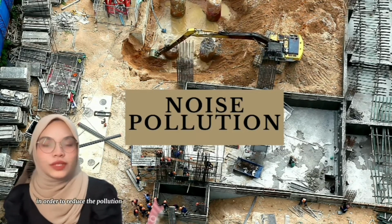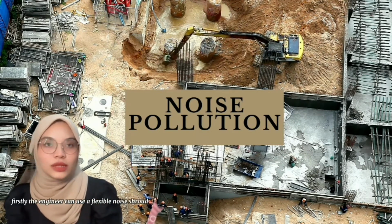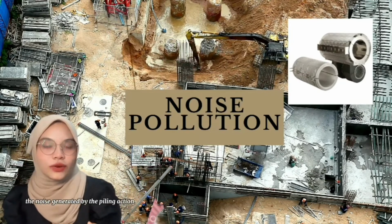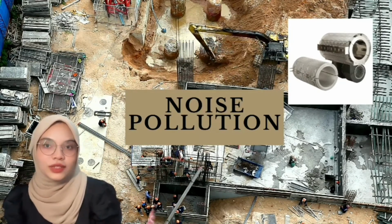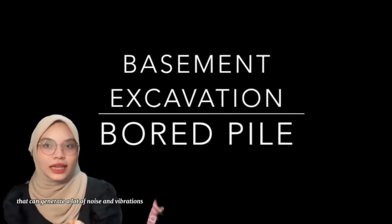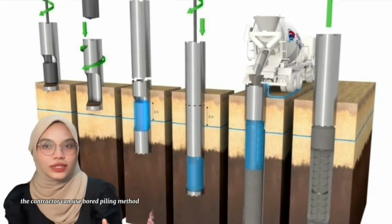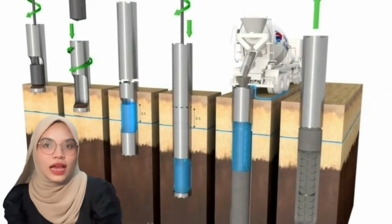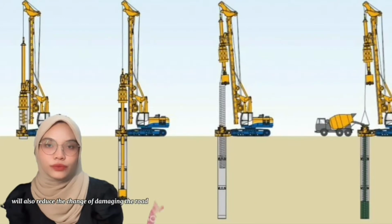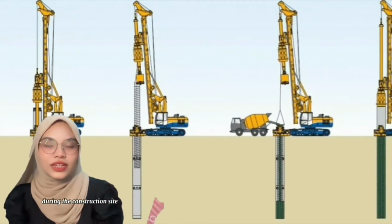In order to reduce the pollution, there are three technologies. Firstly, the engineer can use a flexible noise shroud for piling machines. The shroud will trap the noise generated by the piling action and reduce the sound pollution. Besides that, instead of using a piling method that can generate a lot of noise and vibration, such as hammer piling, the contractor can use the bored piling method. The reduction of vibration will also reduce the chance of damaging the road and buildings nearby and thus not annoy the residents around the construction site.